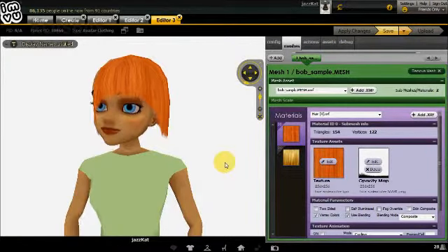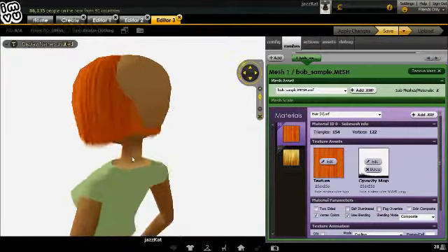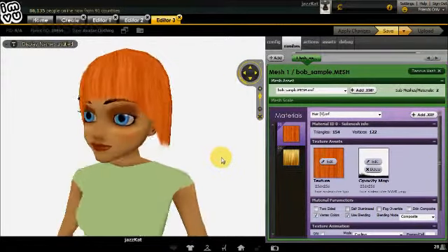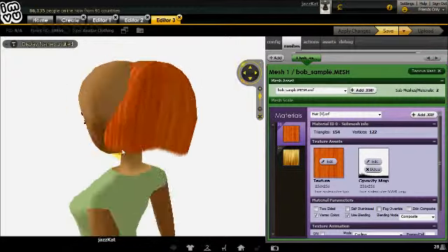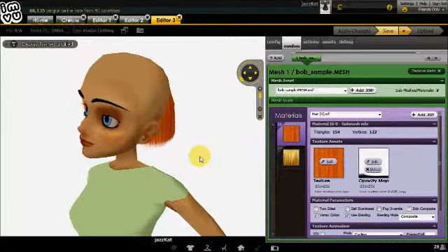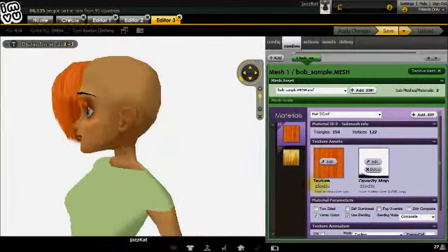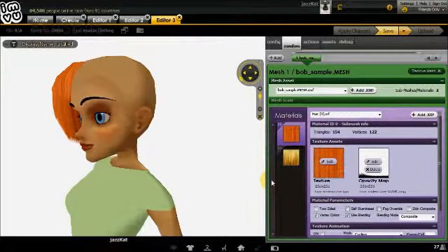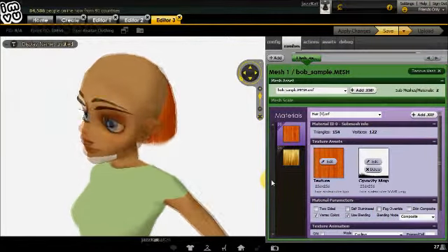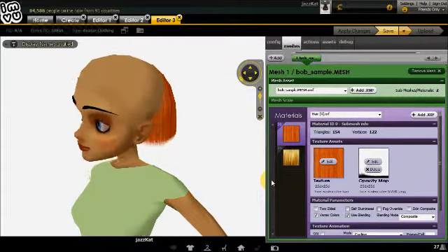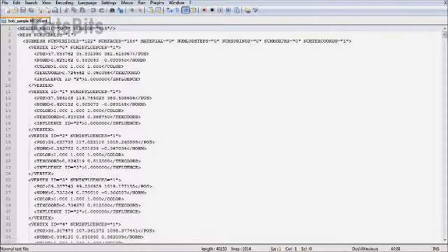So what we have there is a mesh that's in the right place, but it's not being influenced properly by the head. And the only way to fix this is to manually edit the XMF file to change influence, which is the bone name, over the mesh. So open the XMF file into Windows Notepad or similar text or code editor.